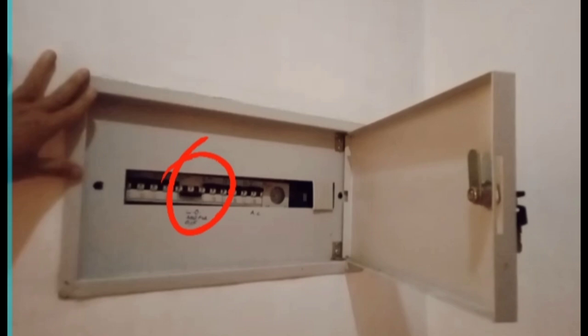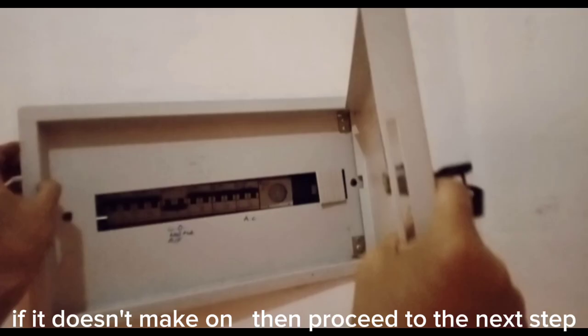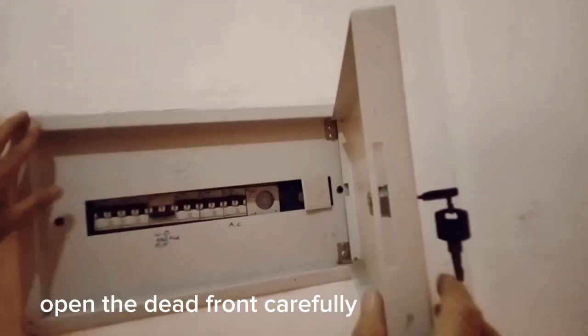Caution! This is not a DIY work. Do not attempt to do this job if you are not a skilled electrical tradesman. First step is to reset the breaker. If it doesn't make on, then proceed to the next step. Open the dead front carefully.